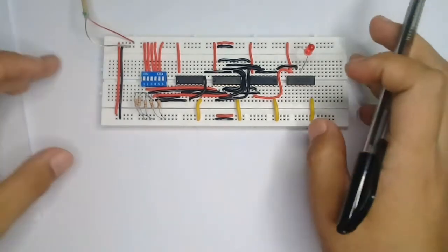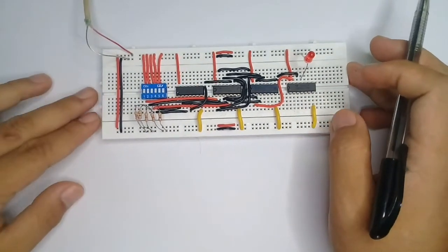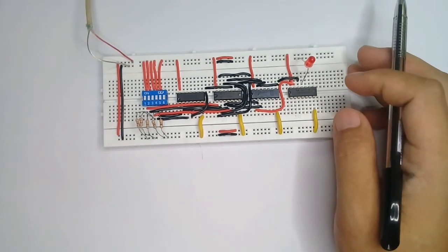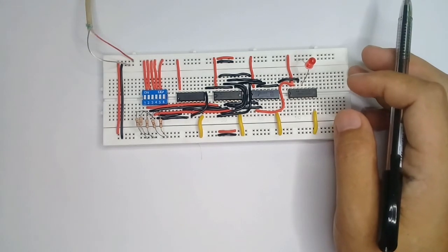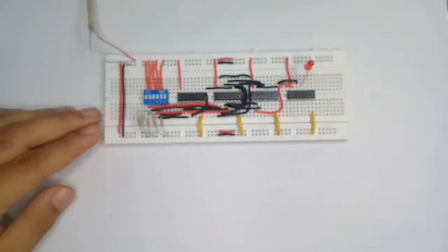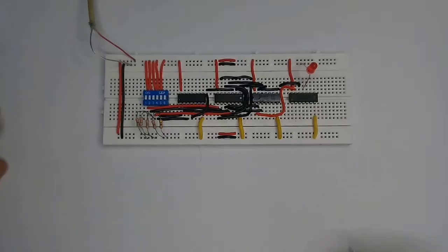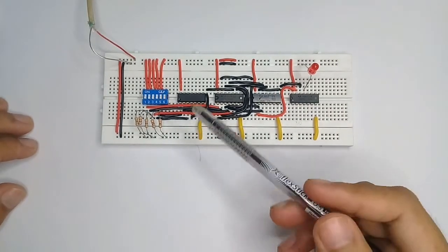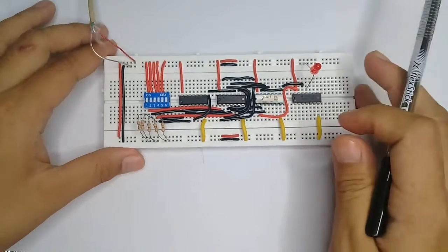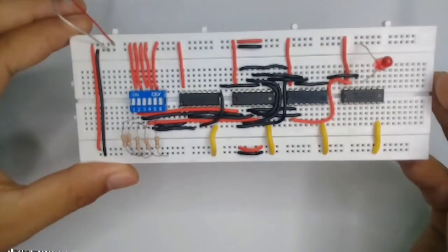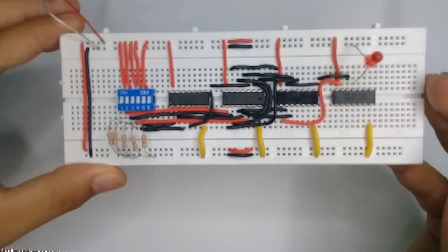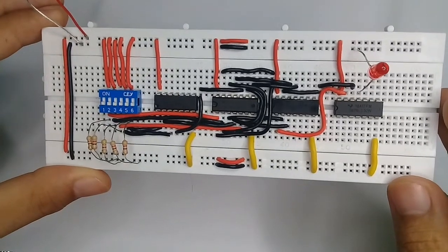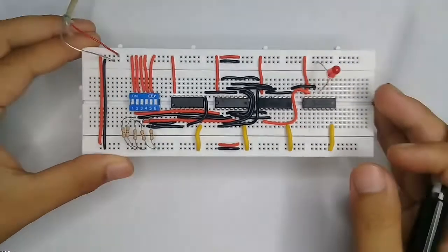So now we have our breadboard. This is our circuit based on the schematic diagram. We just follow all this numbering so we can come up with this circuit. Reviewing our materials, we have a 6 gang dip switch. This is our inverter, SN7404N, and our NAND gate, which is 74LS00N, our NOR gate is 74LS02, and our OR gate is SN74LS32N.